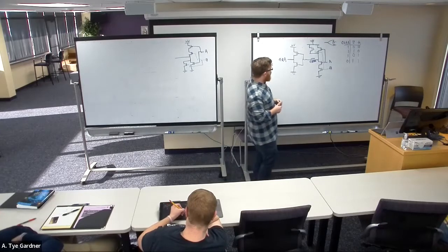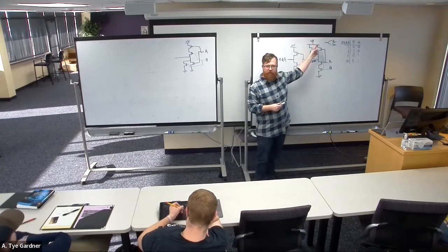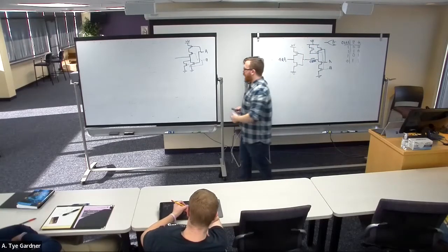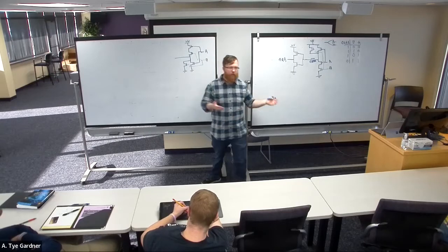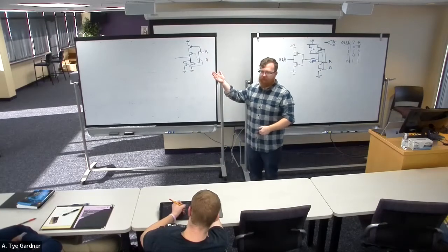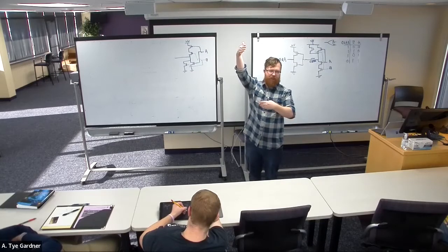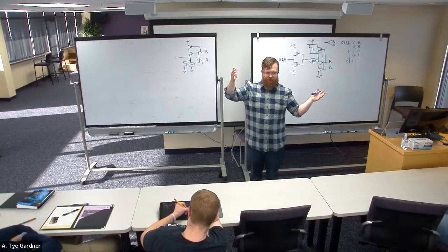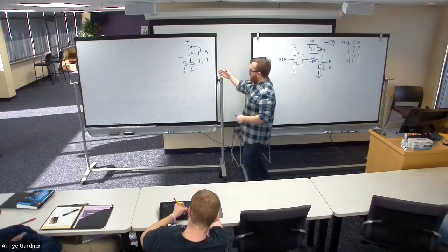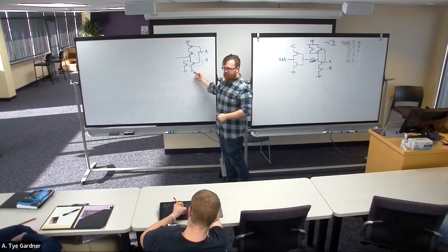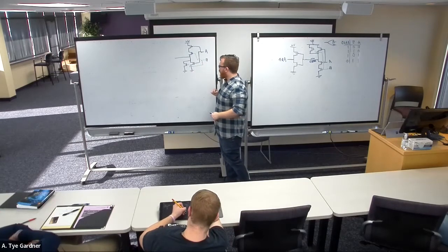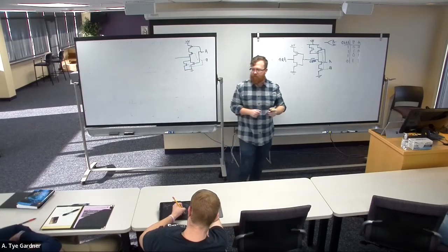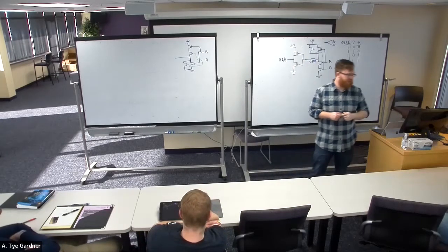Either way is fine. See how this VCC, I just connected them together and they both went to VCC, or I draw them as separate grounds. Both are correct, right? Because ground, just like if I use a symbolic naming, like if I call one thing A on one page and I call it A on the next page, those A's are connected together, unless they're at a different level of the hierarchical design, of course. But this ground is okay. So I could also do that. Right, same thing, just different ways of drawing it.